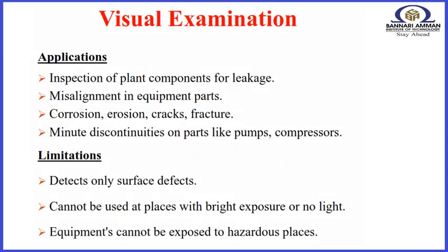Disadvantages of visual inspection. Many variables can lead to discontinuities being missed. At its worst, it relies totally on the human factor. Many organizations pay little attention to the proper training of operators. Subsurface discontinuities will not be seen.